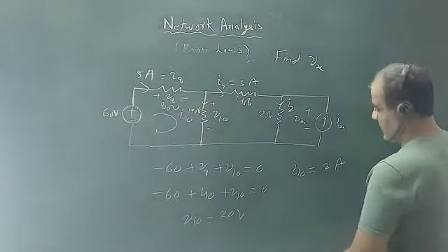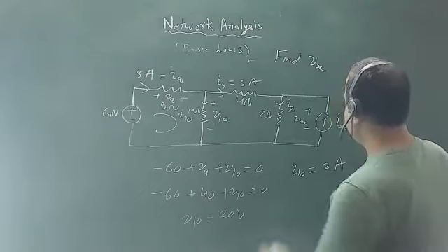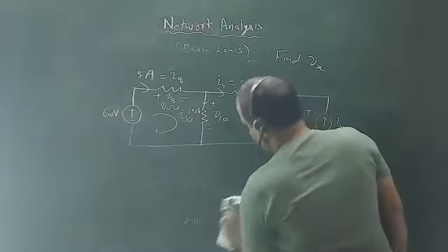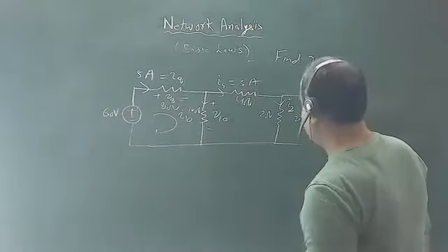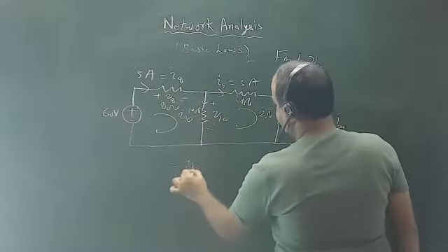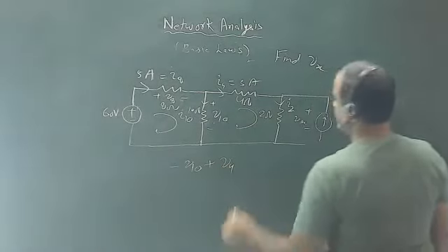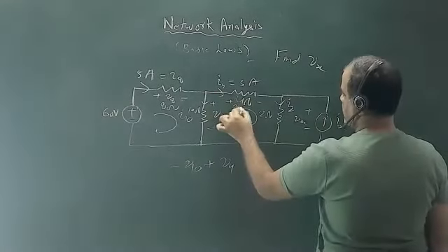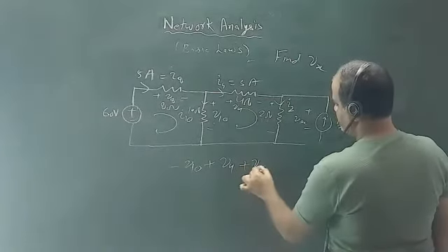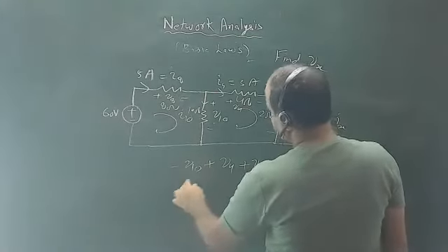Okay. So again, you can apply KVL here and calculate what is V2, how much voltage is dropping here. So if you again apply here, this is minus, okay. So minus V10 plus V4. If you say this is V4, and this is V2, plus V2 equals to 0, okay. Now V10 value we already calculated, 20.